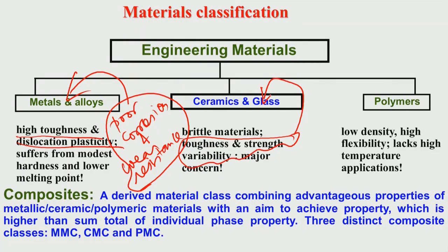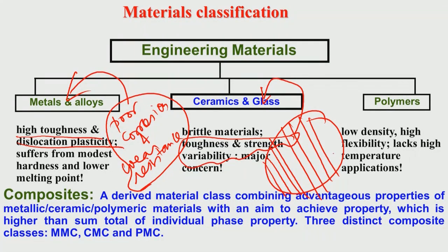Strength reliability means if you take 20 samples of alumina biomaterial cut from the same large alumina disc, each will have a different strength value, simply because strength depends on the crack size and crack size distribution in the structure.